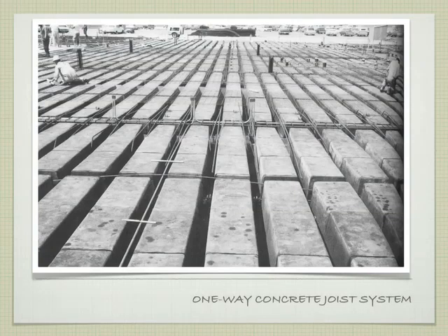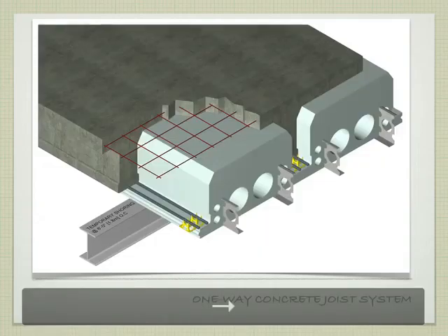So if we look at this example again, we have each of these little domes that have been placed in. We're running our reinforcing in between. Now this has slightly different reinforcing in it, which most of you might recognize from earlier on, that these are little post-tensioning cables that have been put in, but you get the idea nonetheless. The reinforcing would go there. Up at the top here, you can see faintly the welded wire reinforcing that's going to run on top of this system. There's also gaps in between, so this would be the slab band. This smaller gap would be that distribution joist at the midspan.